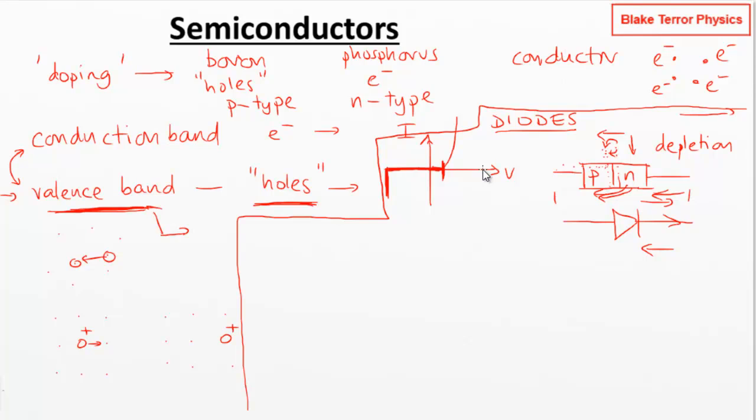But of course, if you put the potential difference the other way round, that just isn't going to happen, because we've got a build up of negative charge here in the n-type semiconductor, which is stopping electrons really coming across this gap. You might have some stuff here in the wires which is, oh yeah, this is great, let's start making our way across here, but it's not going to start rippling through here in the way that it does in the other direction, because you've got this blockage here. You've got this net negative charge which is pushing these electrons away. It's stopping stuff from flowing.